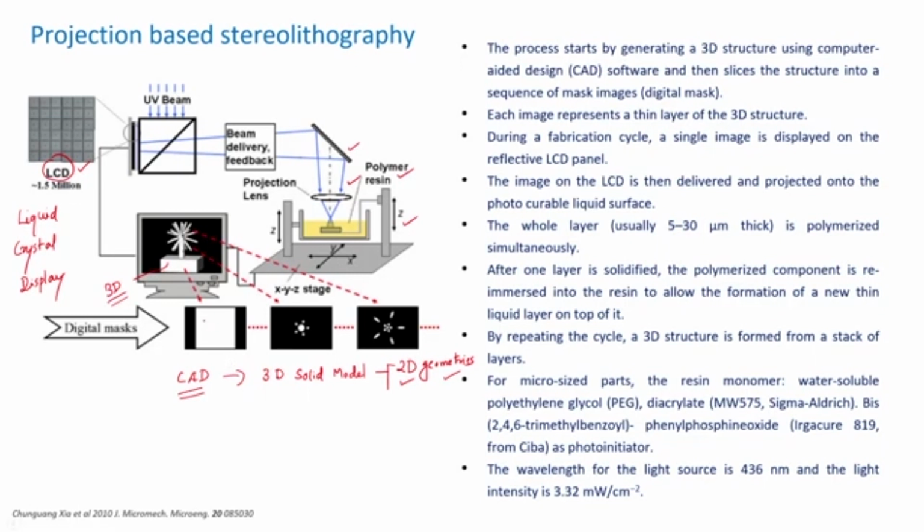At the base the entire portion is white. At this particular location there is a white circular shape and there are white dots around it, and at the tips of that particular product we can see this kind of 2D geometry or 2D slice. Now, this information will be given to the LCD, and the computer generates various patterns and these patterns are given to the liquid crystal display.